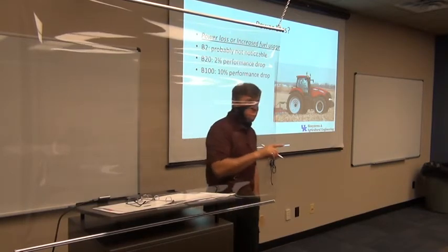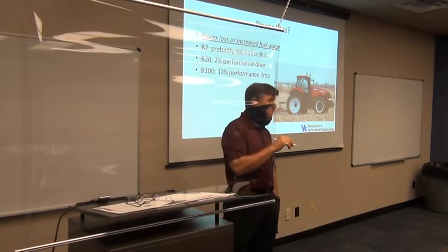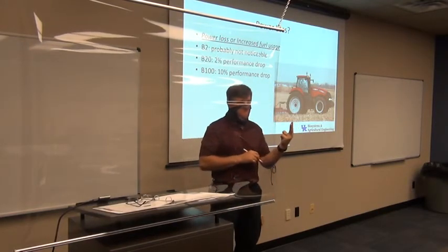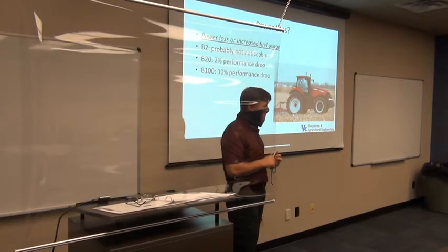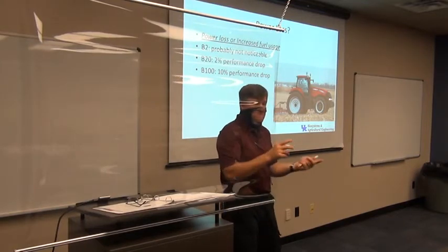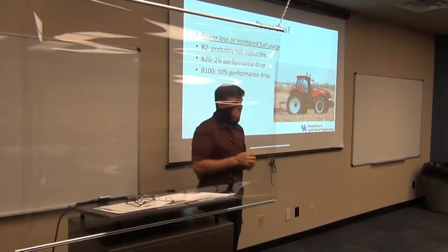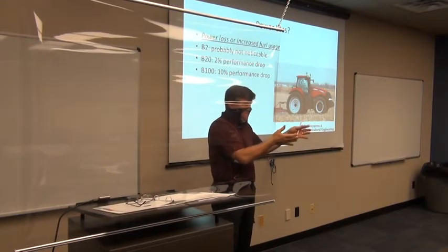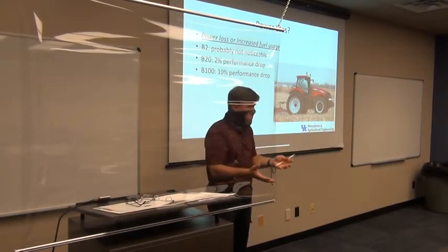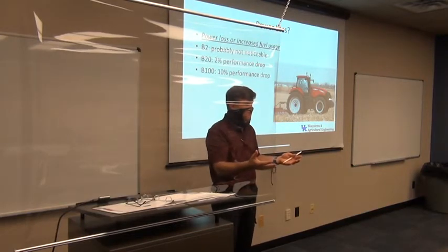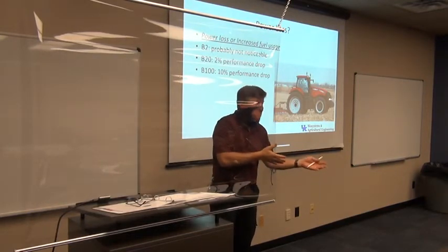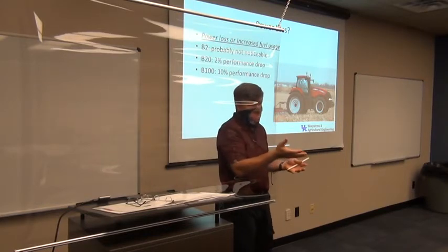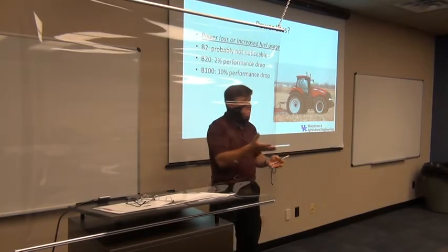And here's one of the things that you're going to try to figure out on Wednesday for our engines down there. There are really two things that could happen when I put a different fuel into that engine, and maybe a combination of those two. So what could happen? Let's say I'm going, like we're doing on Wednesday, to take biodiesel, run the engine, and understand what the performance curve of that engine looks like. Then we're going to stick this cooking oil in. Cooking oil has a lower energy content, lower energy density.